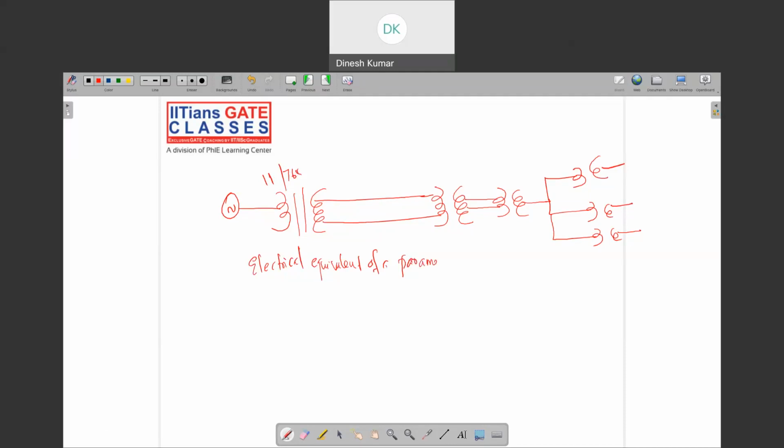That is known as a single line diagram. So we can model the generator as a voltage. Then we take the inductor and the resistor, because we are working at 50 hertz, so the capacitance of these things is irrelevant.